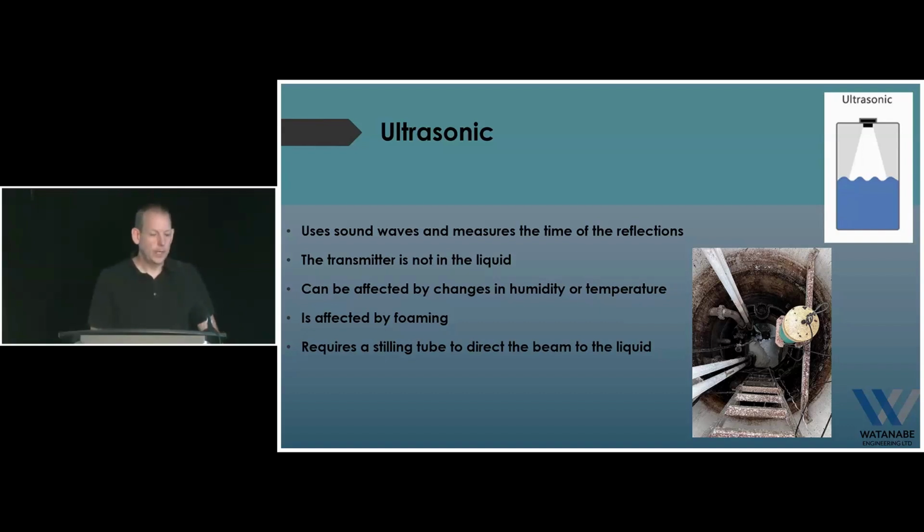So a lot of the time, these sensors have to have some sort of temperature compensation in them. And the other thing I find, and this again is just down to experience, is most of the time that I saw failures on these devices was this time of year where we get the really cold mornings, and then people are showering, you get a lot of condensation, a lot of vapor inside the wet well, and that really interferes with the signal of sound waves. So yeah, the sound is affected by that buildup of sort of steam or gases. It is affected by foaming.